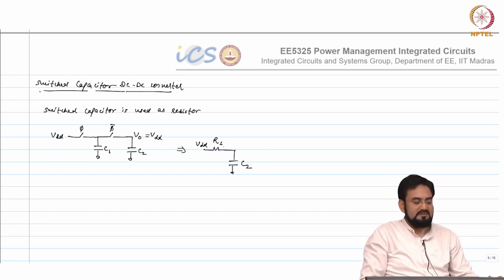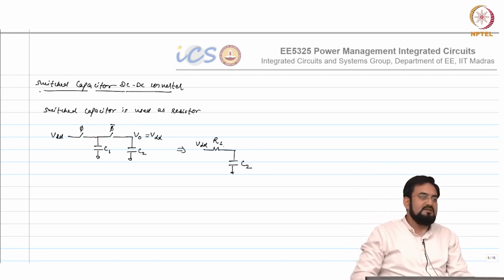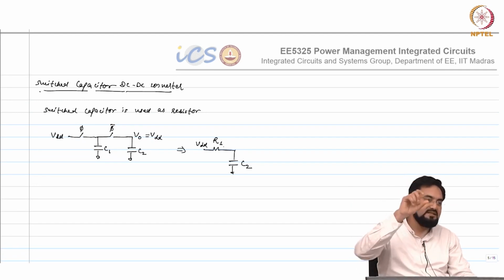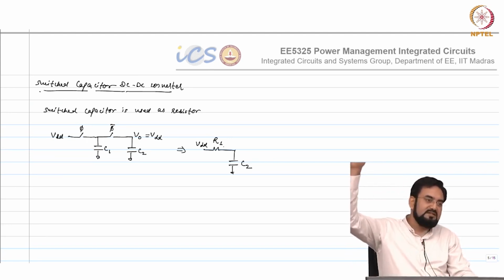You will see the relationship looks similar to an exponential, because the step size is getting smaller, and that is what happens when your output is charged near VDD, it slows down.